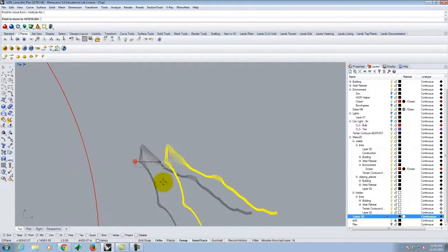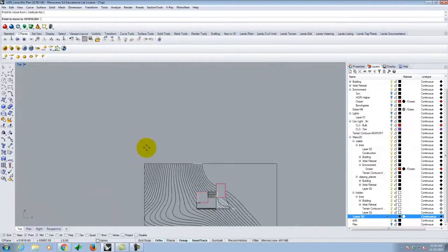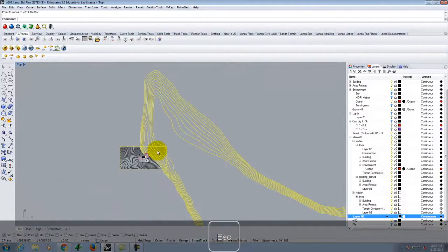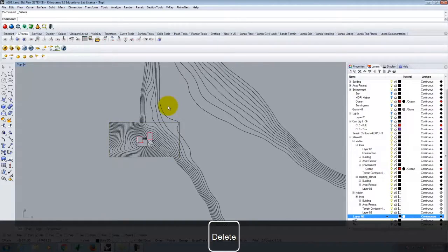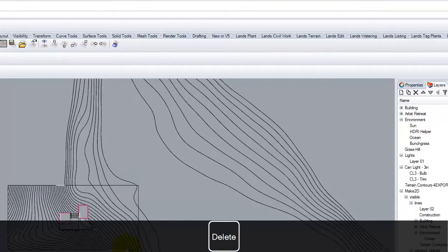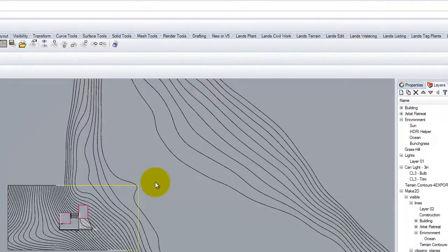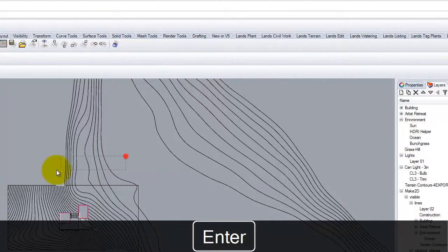And I'm going to line up those rectangles again. Like that, and you see that now I have the other part of this. I can get rid of the extra border, and then I can trim once again. So I just got those lines back because I didn't include them in the first one. So let me trim, and we'll get rid of these.